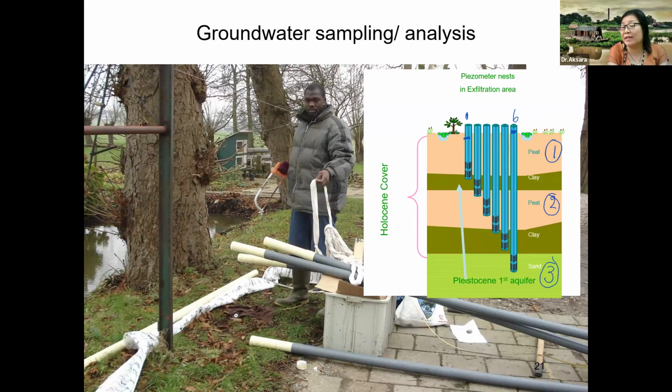Okay, so you probably see that the water level from aquifer 3 in monitoring well 6 has a higher head compared to monitoring well 1, because monitoring well 1 is associated with aquifer 1, which is an unconfined aquifer. So it has less pressure. So you probably see the higher equipotential head in well number 6 compared to number 1. This is just my analysis, okay? But you need to understand that the equipotential head from different aquifers is probably not the same, okay?